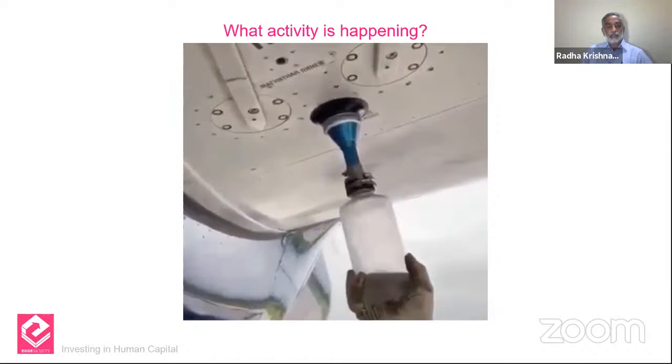But the people who are doing the studies in the college may not know about it. The importance of knowing fuel quantity is something the engineering graduate is fully aware of. If there is water in the fuel, it may not take off at all. And it has happened in India itself. 4 engines shut down during the takeoff run. That was because there was too much water during a monsoon season in Bombay. Think about it. Can we afford that? We cannot afford it. Then we have to know all these things, whatever we are going to work as. Can we go to the next slide, please?